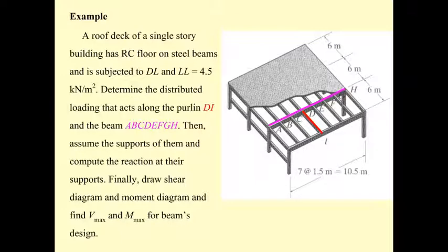The load from the floor will transfer to the small beam, and the reaction from the small beam will transfer to the girder of the frame, and then the reaction of the girder will transfer to the column and then to the foundation of the building.